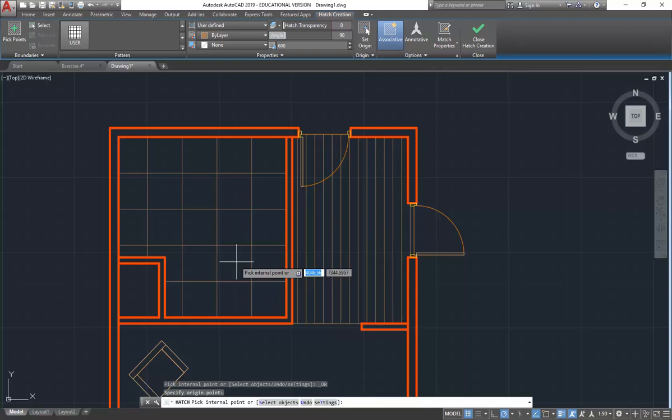Yeah, you want to go around. Well, no, in reality, you would go under a lot of those things, but we don't want to see that in our drawing. So this is not to calculate the tile area. That's slightly different because you have lots of fixtures, especially, say, vanities, that are going to be suspended above the floor, and the tiles will definitely go under them, but we don't want to see that in the plan. So you want to draw the fixtures and the fittings in first, and then hatch around them.